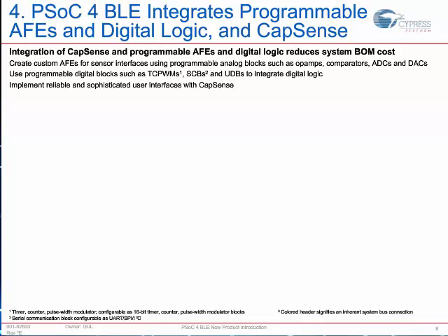PSoC for BLE also has a digital fabric that's completely programmable. This is a CPLD-based digital fabric where you can either exercise it by using pre-built components that Cypress provides in the library, or by even writing your HDL or hardware description language in Verilog inside of PSoC Creator. So think of it as this separate fabric of the chip that's very well integrated with the CPU and the memory and allows you to exercise some deterministic hardware control and communications inside the same chip.